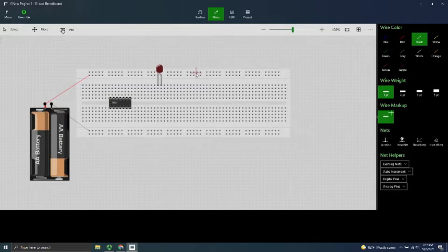So let's go ahead and wire up our LED. So an LED, we've already discussed this in lab. You should know that one side needs voltage, and the other side has to be grounded. And so I'm going to go ahead and ground our cathode right here.